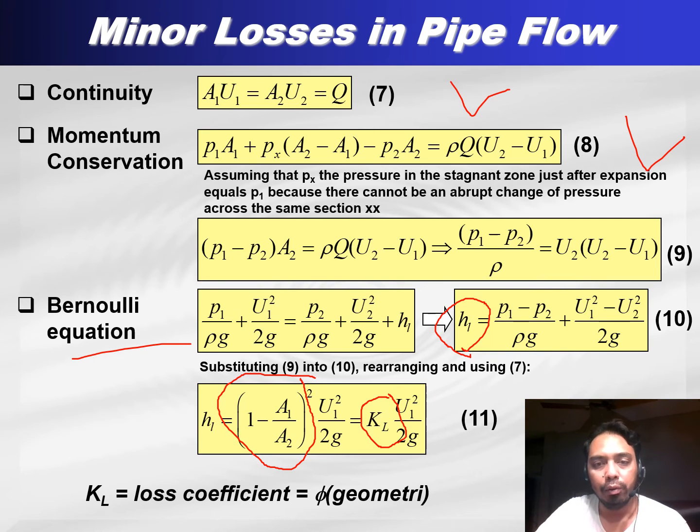So when we want to calculate the total pressure drop of a flow in a pipe, we need to consider both the major loss obtained from the Darcy-Weisbach equation and the Moody diagram, and also the minor losses due to contractions, enlargements, bends and everything else to top up with.